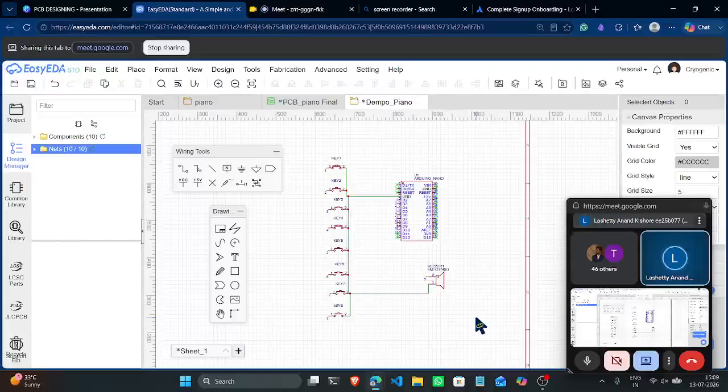And this thing is made by two companies, and both companies' footprints are different. They keep their pin arrangement differently. And you have the component from company X. By mistake, while creating your PCB, you use the pin arrangement of company Y, and you send it to your manufacturer, and your PCB comes to you. So now the issue is the pads for the 555 timer on the PCB won't match with the component that you have with you. That's an issue, right?